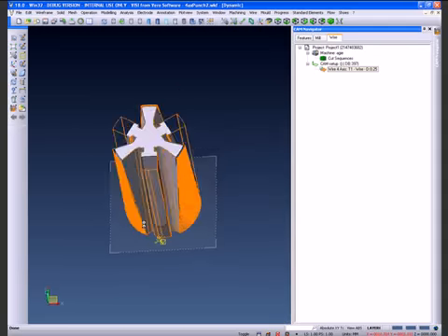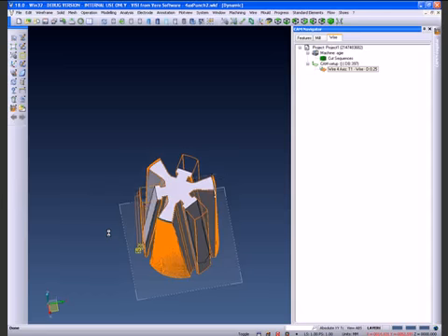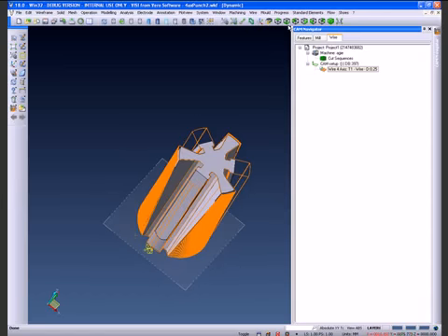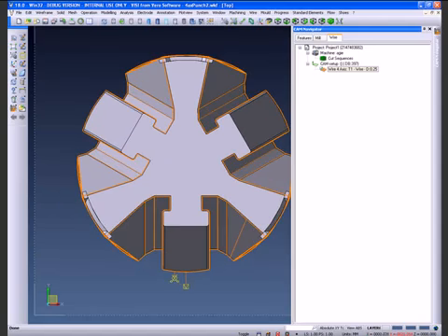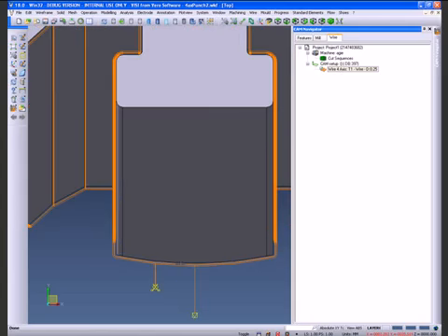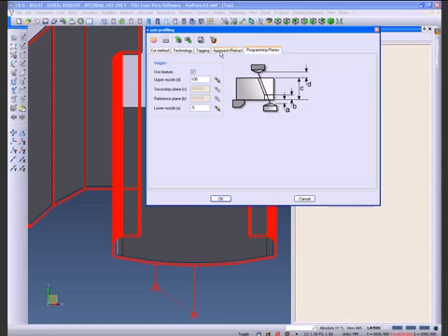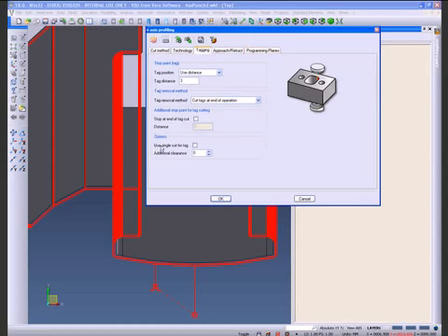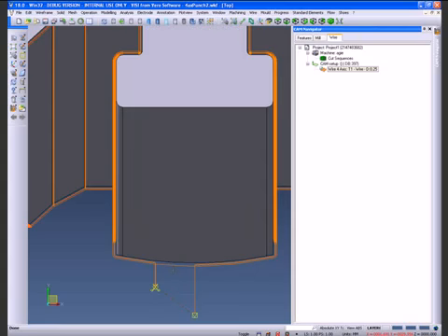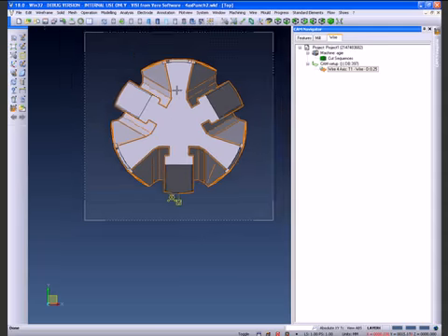We can now see that we have our triple cut toolpath and a tagging operation available to us. Now this tagging at the moment is doing triple cut on the tag itself, but in some cases you might find you want to go in and modify this so that you can grind the tag later and just use a single cut for this part of the operation only. We have an option down here just to tick the box to enable you just to get a single cut for tagging only. Now we have the 4-axis wire path that we require.